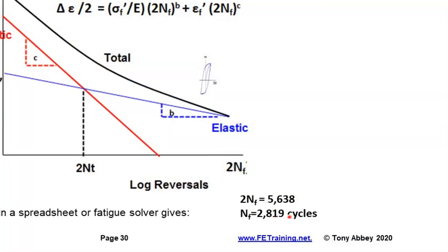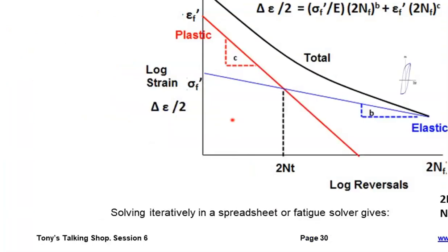If I saw that and somebody had run a high cycle fatigue, I'd think, okay, you're kidding me, because you've used this curve to try and give me a life over here somewhere, and I don't believe you, because there should have been a plasticity effect. So for me, somewhere below 50,000, I always get a little bit suspicious. I'm an older suspicious character, so I don't use a number. I use the presence of plasticity.